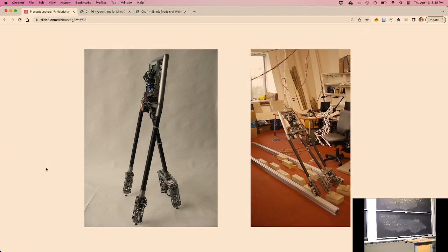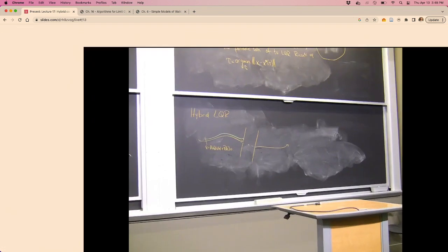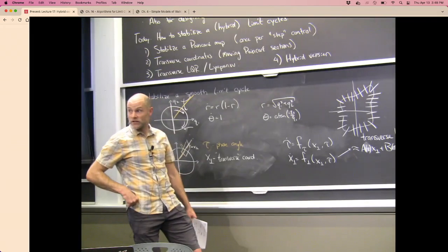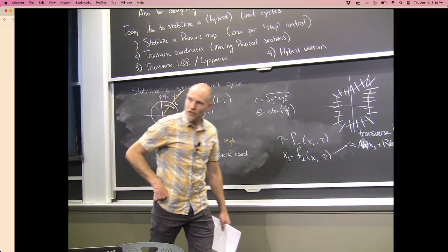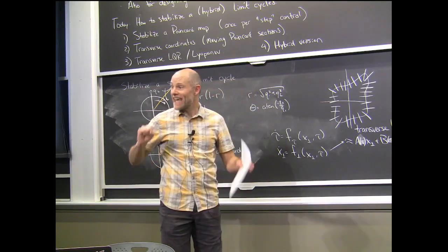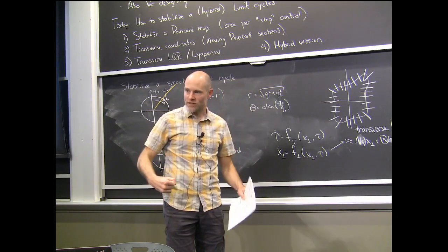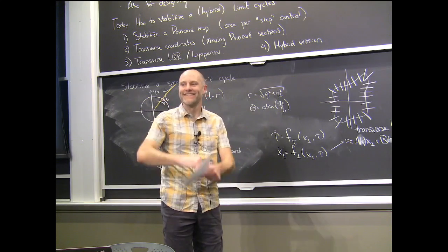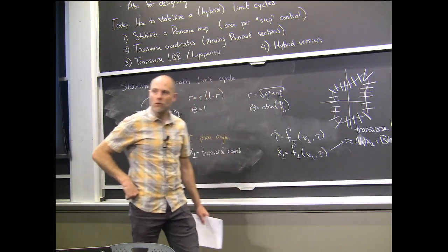But one of the things that happened in that model was, it also had a hip torque, okay? What happens is that the thing you want to do right before your foot hits the ground is to apply a particular torque in one direction. The thing you want to do after you hit the ground is exactly the opposite thing. Like the gains on your hip torque change dramatically at the moment of impact.